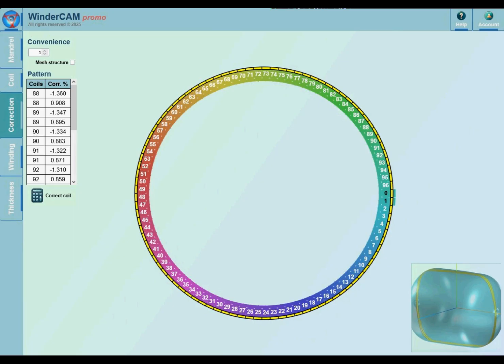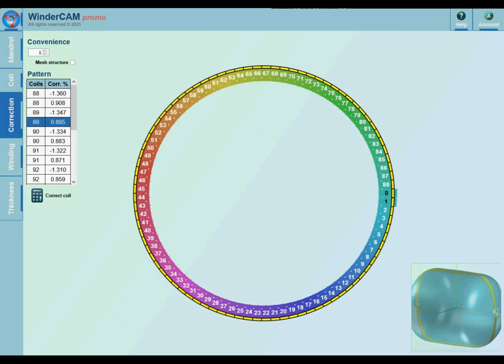That brings us to the correction stage, right? Exactly. Step 4. Winding path correction. Here we ensure uniform coverage for a smooth, continuous layer. Shells with a winding period close to 2 pi present a specific challenge, the polar region.